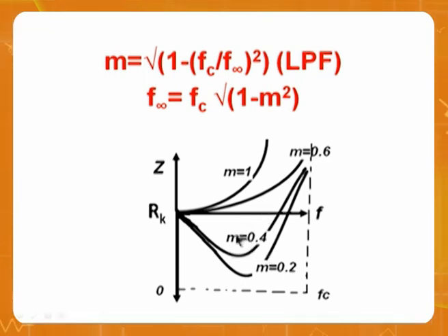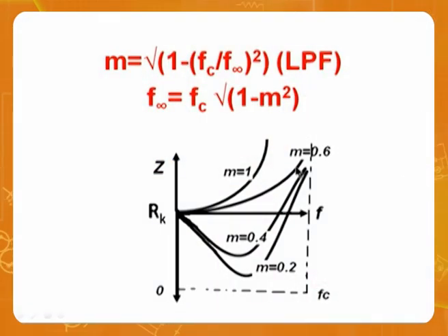And you look at M is equal to 0.4, M is equal to 0.2. You know what these things actually are? These belong to M derived filter. That means M derived filter becomes worst as far as impedance is concerned. That's why the best is half section, somewhat okay is constant K, but M derived is worst of all. So M derived, the purpose is not for impedance, it is for alpha, attenuation to increase sharply.